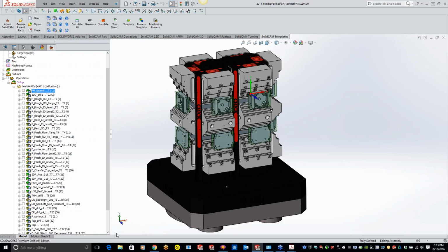Very nice. All right, who was asking the tombstone question? That was actually John Zitzkis. Okay, so John, I got a tombstone part here, and I'll go through some of the tombstone milling right now, and please let me know if I didn't cover what you're asking. I think you're just asking for work offsets on a fourth axis.